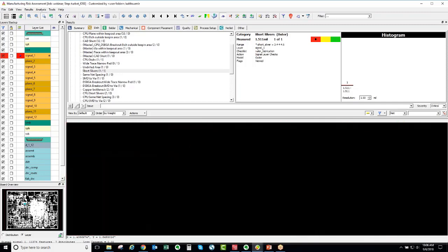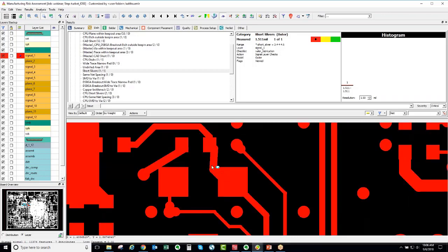But obviously in this design, we intentionally put some errors in there, but many designs that people create out there will have these types of violations. Fabricators will usually go fix these on the fly and never even tell you. Some fabricators will give you back a report saying, hey, we had to fix these items. But if you specifically specified in your drawing that you're not allowed to modify data, then that's going to hold up your design from fabrication if you're not validating these types of small violations or design issues beforehand.